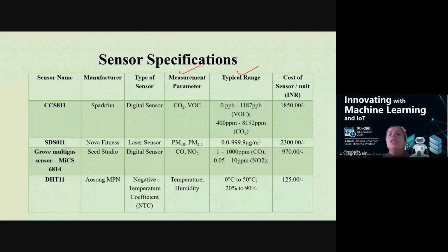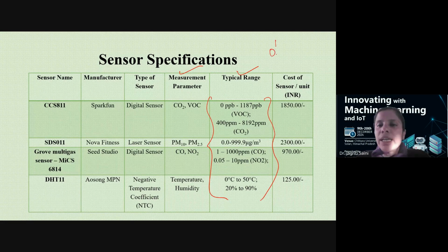So this is how the hardware-based studies we take up, and then we start a decision about their deployment by considering all the relevant parameters. Along with the things listed here, you will find one more important thing that we call operating range, which is currently not mentioned over here. There are two things: one is measurement range, the other is operating range. Always remember this whenever you buy a hardware sensor unit for any of your projects.